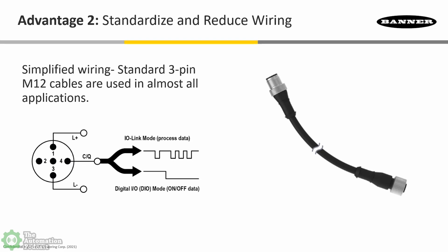And now you just don't have to worry about having these big bulky cables anymore, like your M23 or 19-conductor cables. And what this often means too is no more wiring or pinout mistakes, more cost-effective and readily available cabling. And this is big, much faster installation times. And this is one of the big reasons I've seen many users switch to IO-Link.